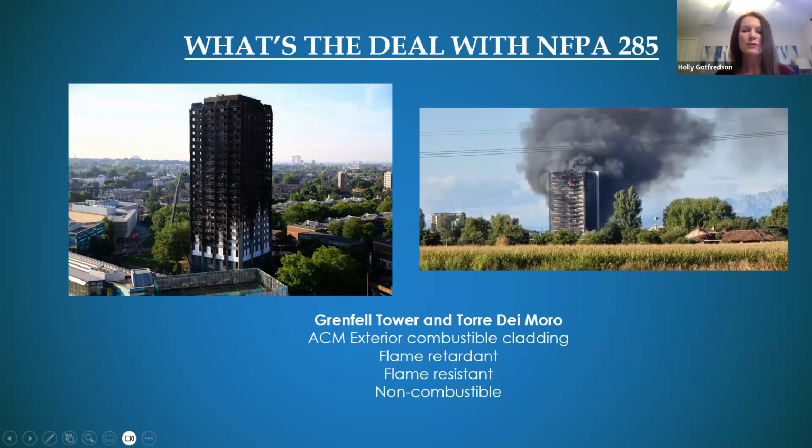So when you're considering different types of exterior cladding, you may have less expensive options. The right option may be a little bit more expensive, but you definitely want to consider the safety of the occupants and the longevity of the building. Solid aluminum plate panels are a great way to go because, again, they're non-combustible, they don't burn. It's just a great product where you can really feel comfortable about that choice for your project.